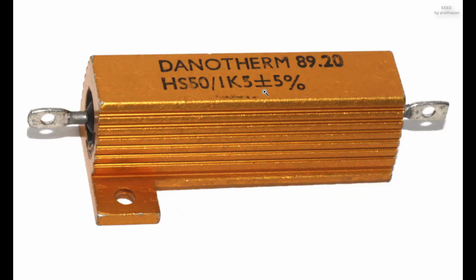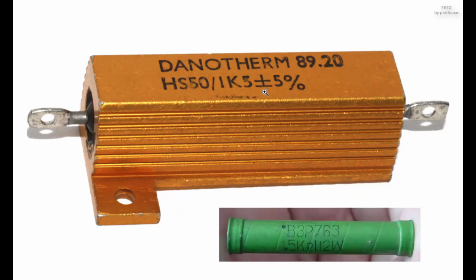Non-ideal properties. Practical resistors have a series inductance and a small parallel capacitance. These specifications can be important in high-frequency applications. In a low-noise amplifier or preamp, the noise characteristics of a resistor may be an issue. VZR power resistor 1.5 kΩ 12 W, manufactured in 1963 in the Soviet Union. The temperature coefficient of the resistance may also be of concern in some precision applications. The unwanted inductance, excess noise, and temperature coefficient are mainly dependent on the technology used in manufacturing the resistor. They are not normally specified individually for a particular family of resistors manufactured using a particular technology.